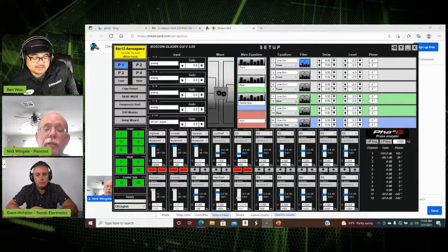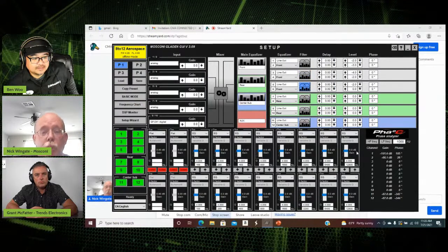That's the reason why in all of these filter sections, you see all these EQ bands. That's the reason it's here, so you can make sure that every single solitary speaker you are working on has the same amount of energy being reproduced at the exact same time. Because if we don't have it all set as close as possible, then I don't care how much delay you do, it's going to be wrong. If you've got too much energy in high frequencies versus the mid-range playing lower, guess what? It's incorrect, because you really and truly want a flat line.